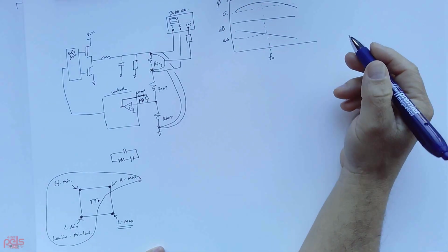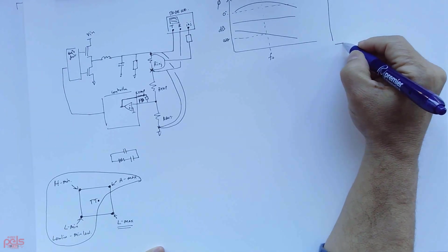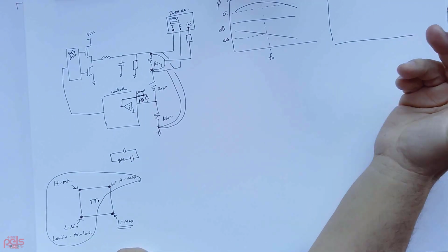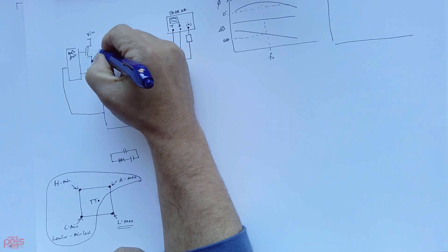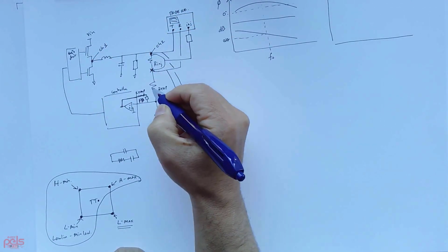When I make this measurement, I am also using a scope to get the switching node. So this typically goes to channel 1, this goes to channel 2 of the scope.